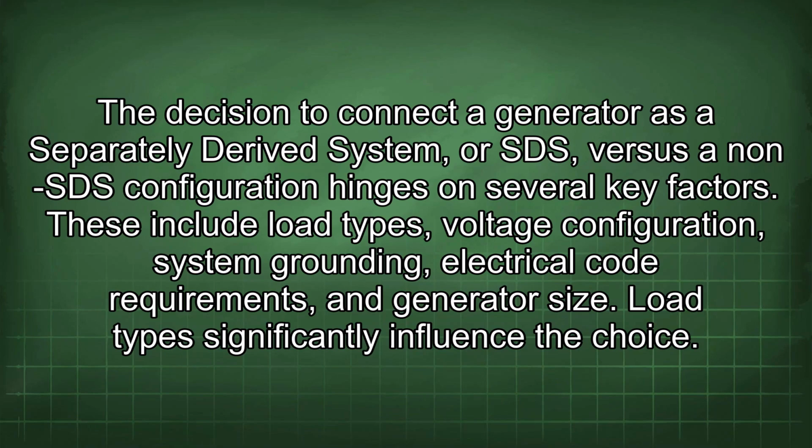The decision to connect a generator as a separately derived system, or SDS, versus a non-SDS configuration hinges on several key factors. These include load types, voltage configuration, system grounding, electrical code requirements, and generator size. Load types significantly influence the choice.